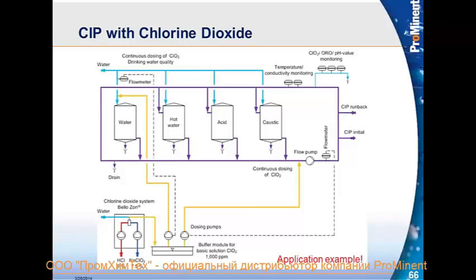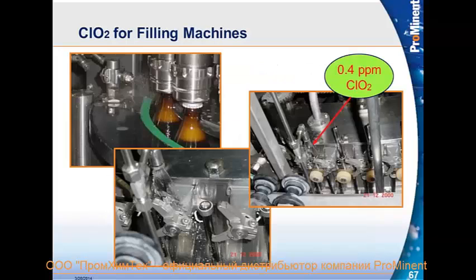And once again, in some of these piping systems that you see in these applications, there's always a chance of biofilm being formed in older piping systems and dead legs. And from biofilm could possibly come Legionella. If you have a little bit of chlorine dioxide in your water system, it will completely eliminate the biofilm after time, depending on how bad the biofilm is. And we've seen piping systems completely clogged with biofilm. The chlorine dioxide will do a great job of keeping the biofilm from coming back once it's eliminated.